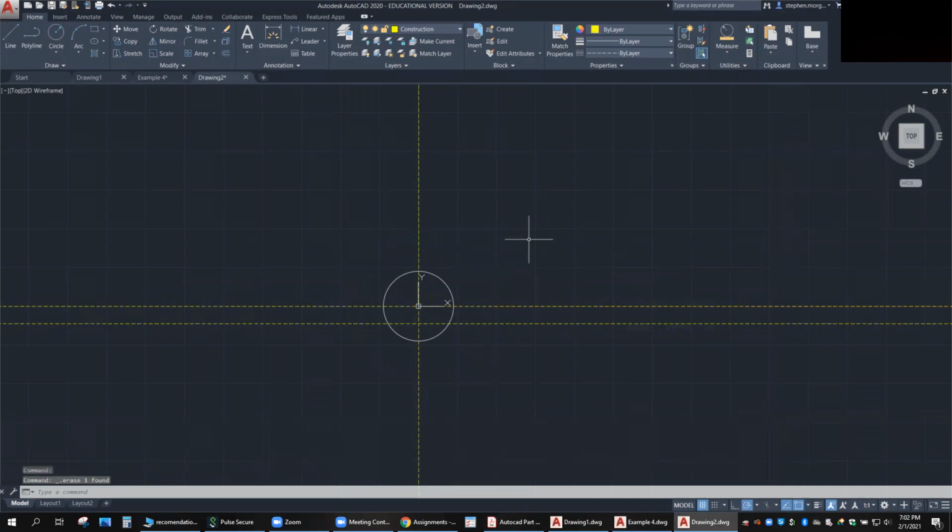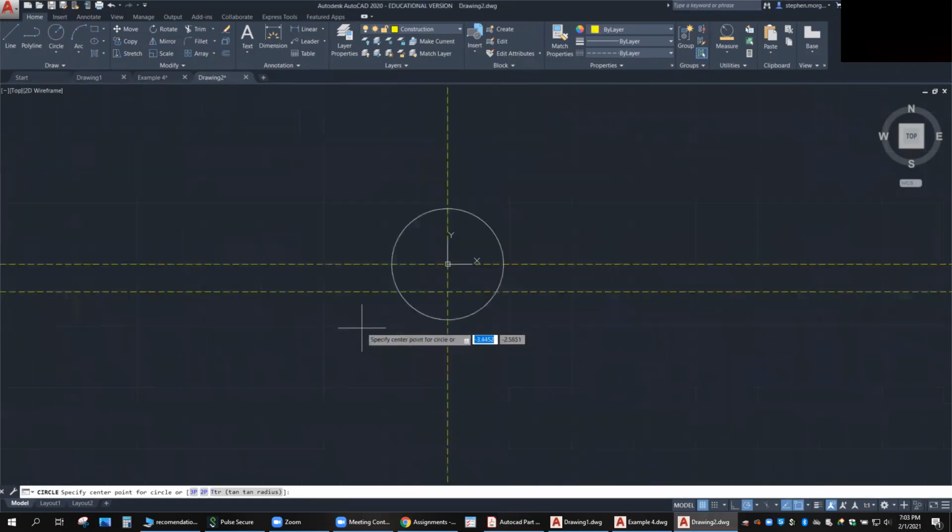I used to be really crazy about double checking all my work when I worked in the sheet metal industry because we worked with really expensive material and we had a really big laser cutter. If a simple mistake like dimensioning a diameter when you thought you were dimensioning a radius, or vice versa, could cost thousands of dollars of material.